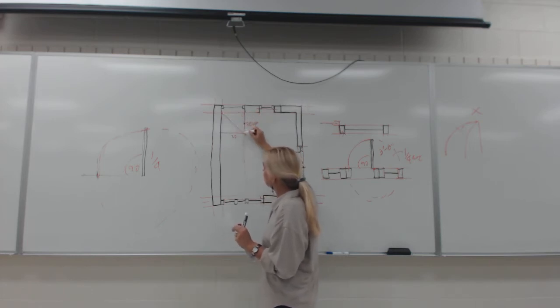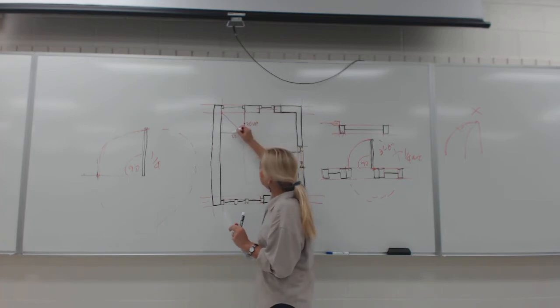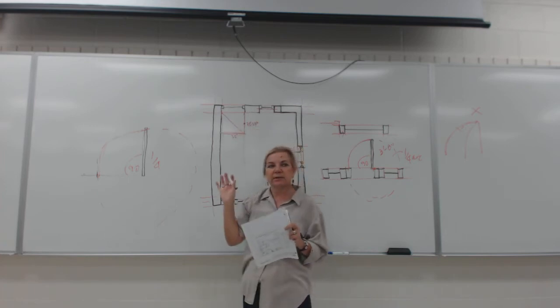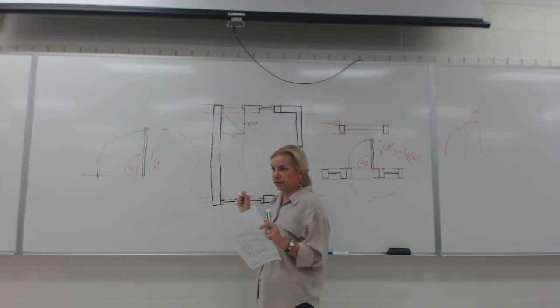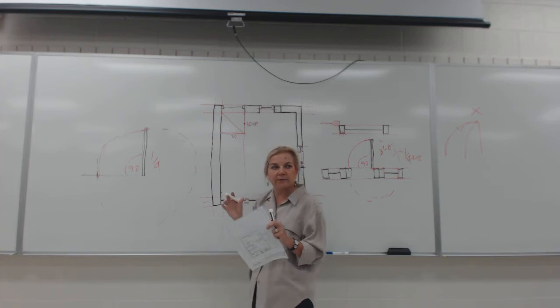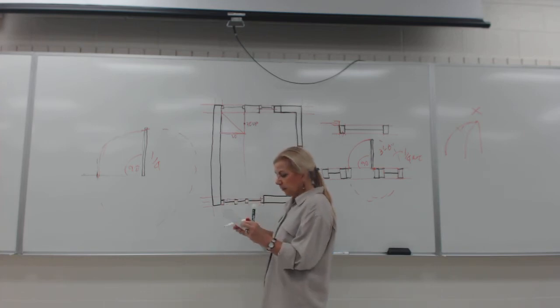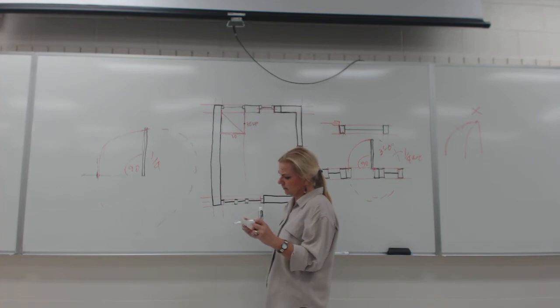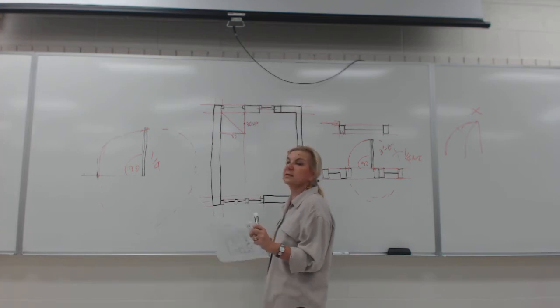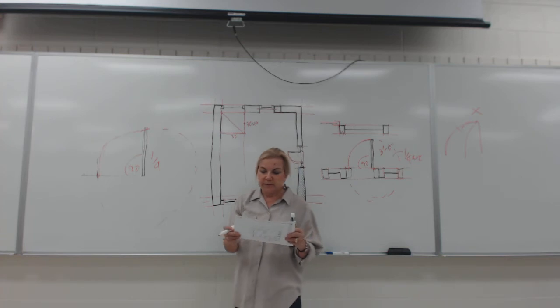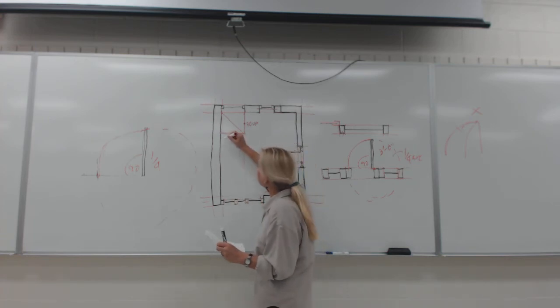Second riser is on 45-degree angle. And then where the straight run stair starts, we already made almost 8 and 8 inches, okay? 3 times 8. So this is a very compact, very well designed stair. Then we have a note that says 9 risers at 9 inches. There are 9 risers, so we have 9 lines.